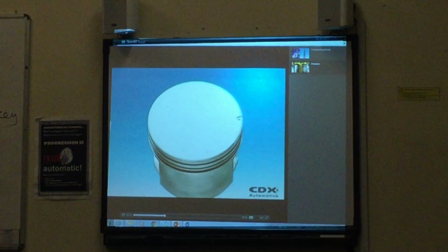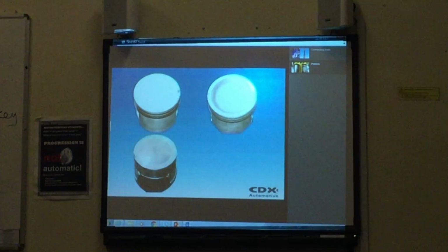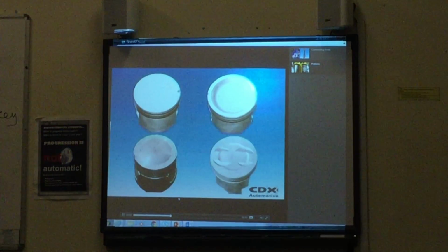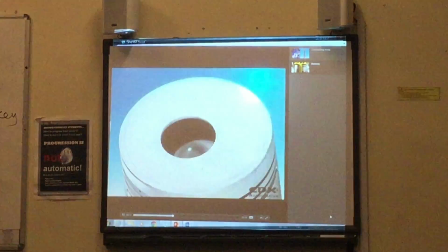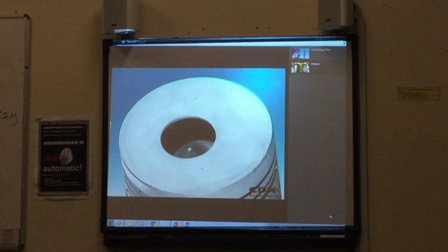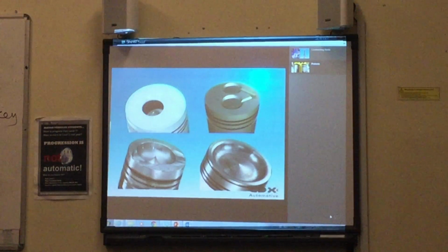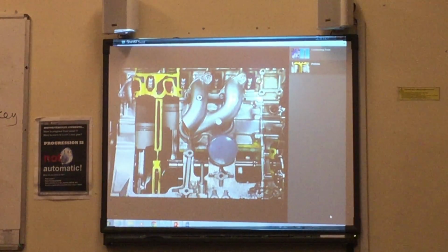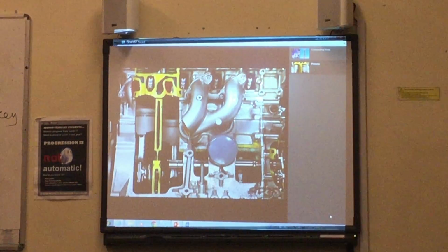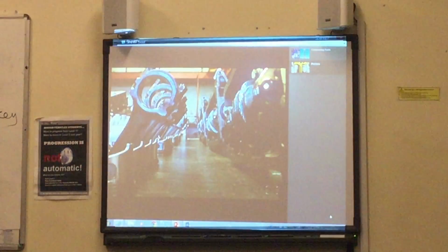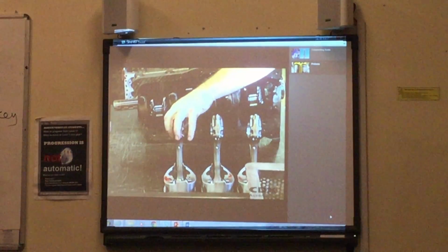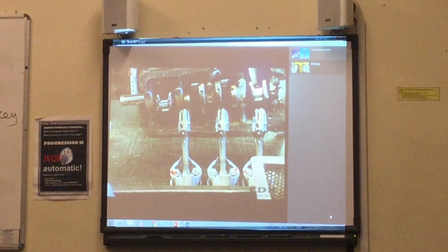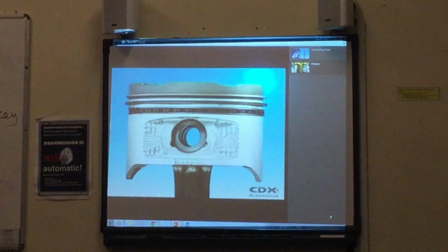The piston crown may be flat, concave, domed, or recessed. In diesel engines, the combustion chamber may be formed totally or in part in the piston crown, depending on the method of injection, so they use pistons with different shapes. The piston must stand up to great heat and pressure. It also must change direction from about 10 times a second up to hundreds of times a second. In most engines, the weight of the pistons is important for engine balance. This is why pistons should only be replaced in matched sets. Some pistons are forged, while others are cast aluminum alloys.